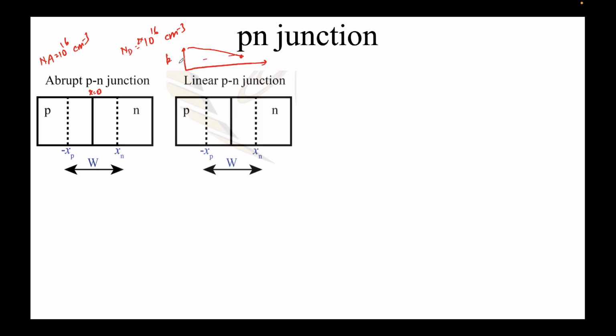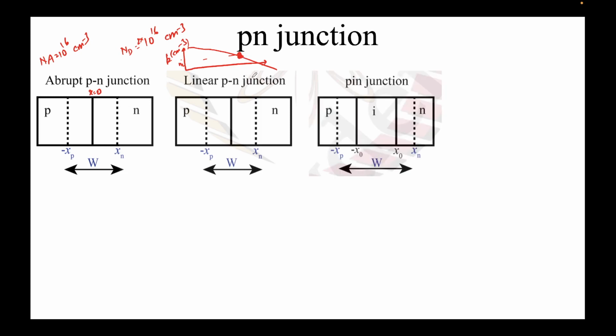So this is your Ni, and then here naturally it will fall below because it's entering the n type. And the reverse is true for the electron concentration. So this is hole concentration. Electron concentration will rise, and in the middle at the metallurgical junction it will naturally be Ni, the intrinsic concentration.